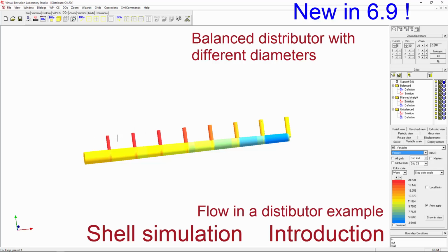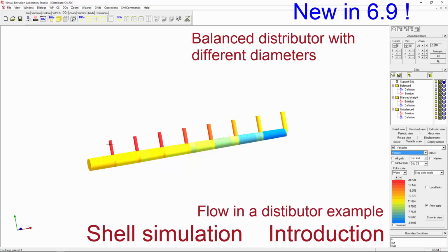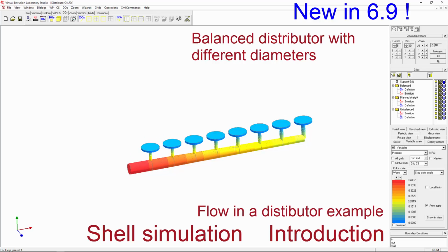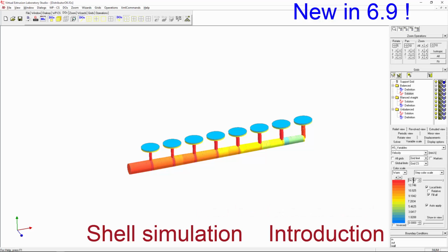Again, we have high velocity here, but the velocity doesn't matter. What matters is the mass flow rate. So we need to multiply by area, and then we get whether the mass flow rate here and there is the same. Well, I know it's a little bit more calculation. That's why I've prepared a very small trick that I have added at the top of each of those pipes: a small extra segment which doesn't consume any pressure, so it won't have influence, but it has the same diameters, the same area. So now we can just look at the velocities, and if the velocities here are the same, we will have the same flow rate in those sections.